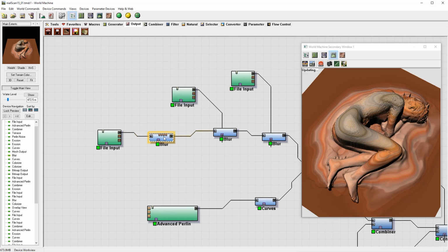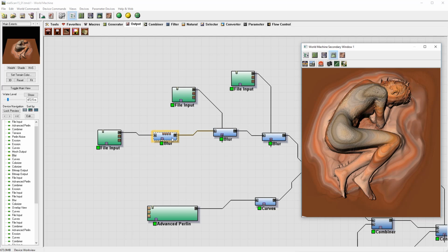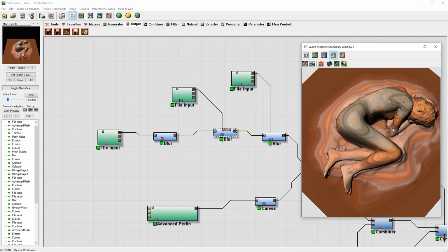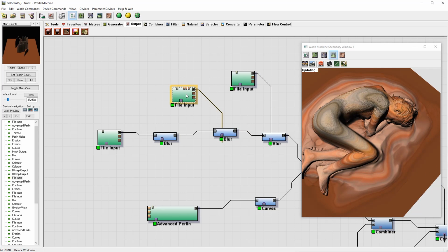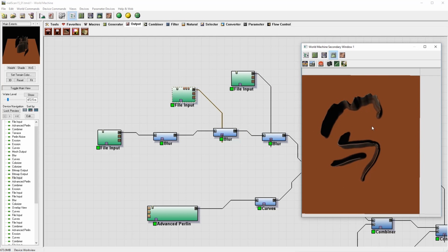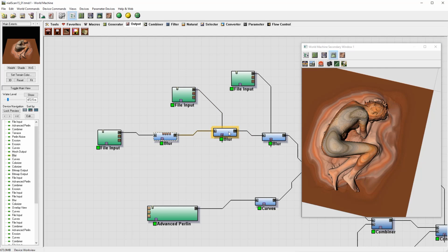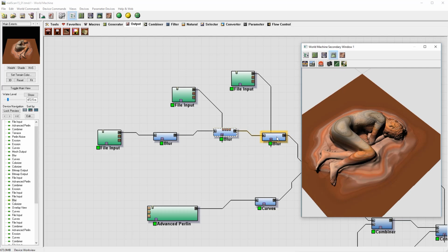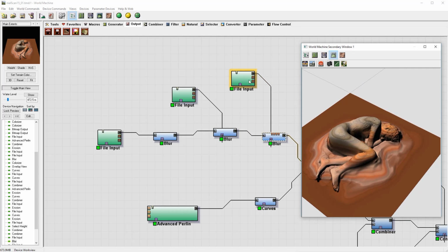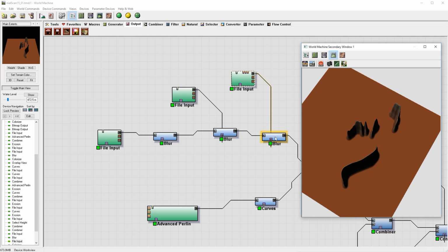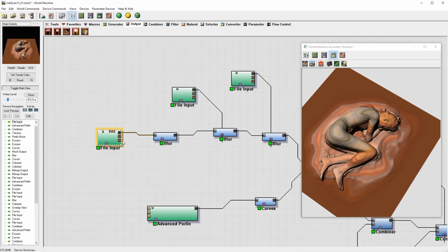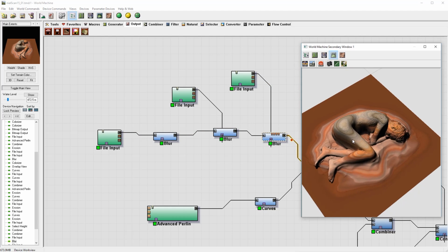So here is the basic input of my elevation map. I will add a few bumps just to blend the body a bit more into the ground, because in the parts where there is too much contrast in the elevation, you start to see some artifacts. So here I just masked some areas to put some blur. You can see here the mask. So you can see here the body starts to blend a bit more into the ground already. It will simplify the process of the erosion afterwards.